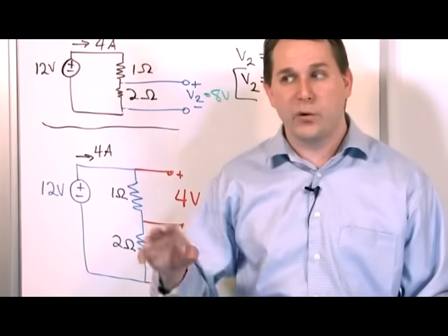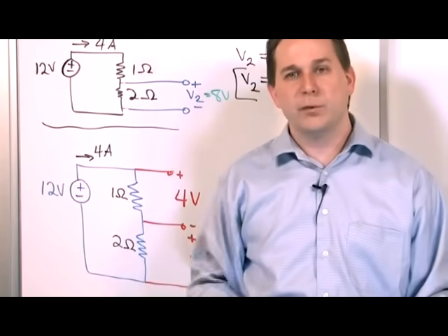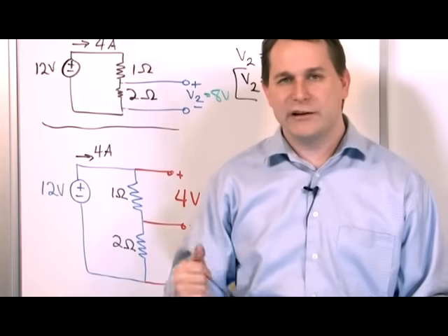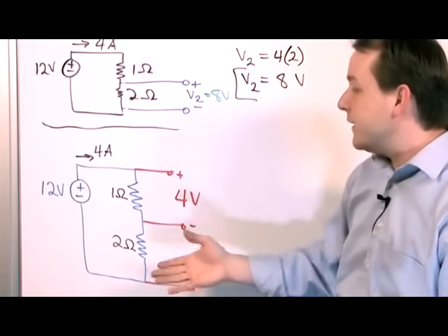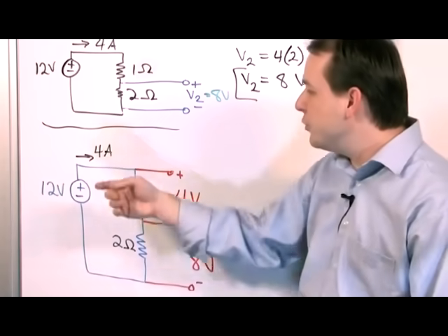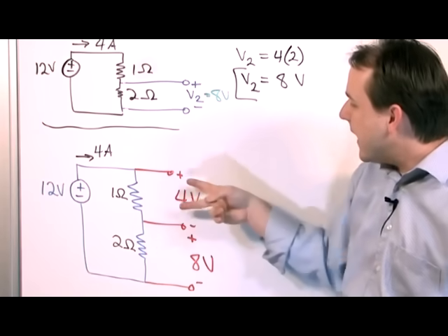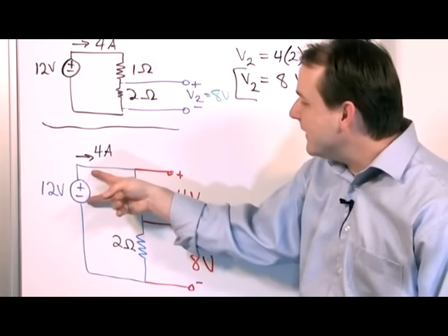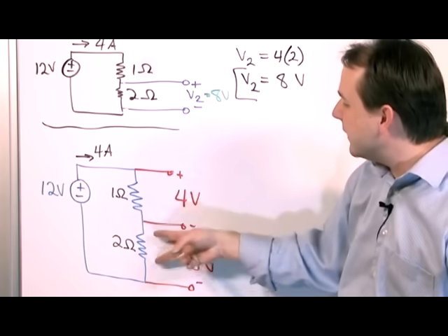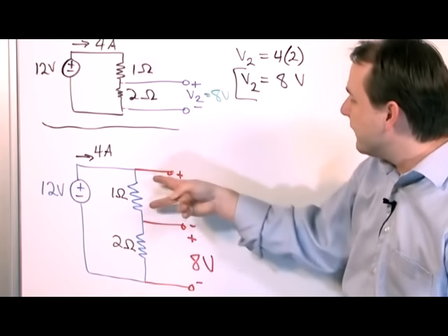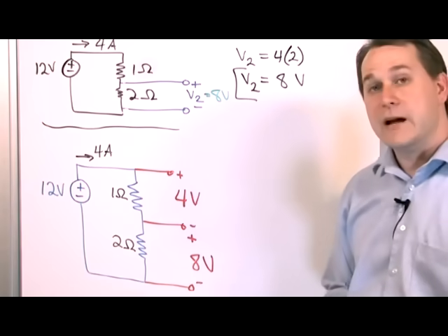Maybe if you put more than 4 volts on this part of the circuit way over here, it'll blow it up, right? Maybe it's a delicate chip or something like that. So you could, and if all you had was a 12 volt battery, then you could construct a voltage divider like this. You would have 4 volts here. You're basically taking the source and forcing it to be split up so that 4 volts lies across this guy, 8 volts lies across this guy.